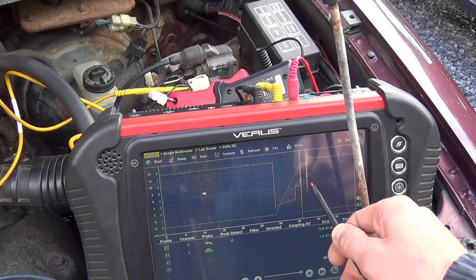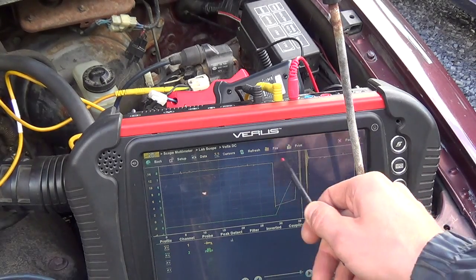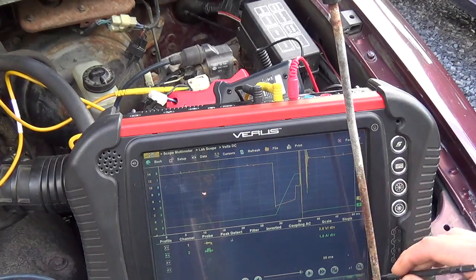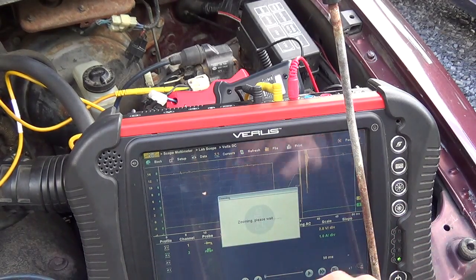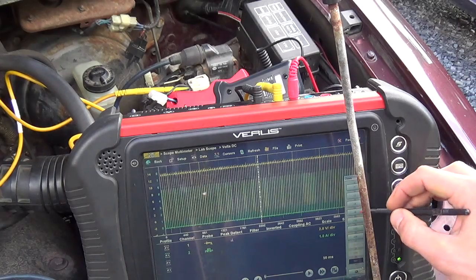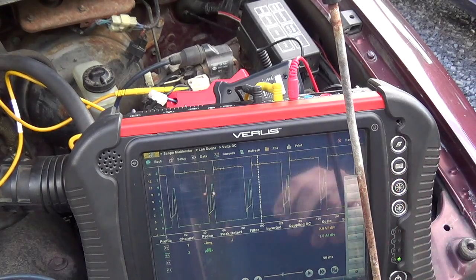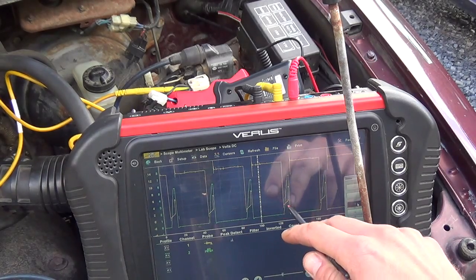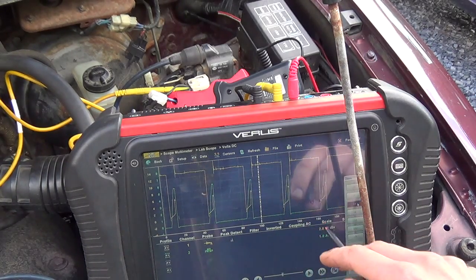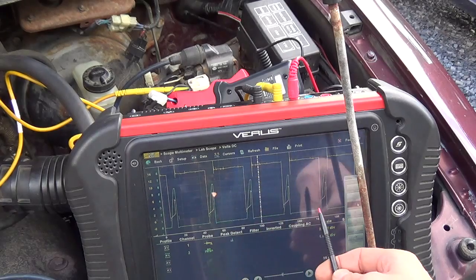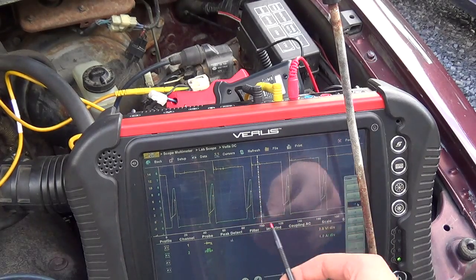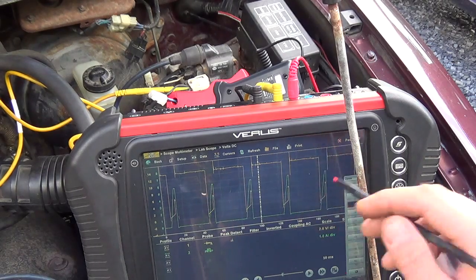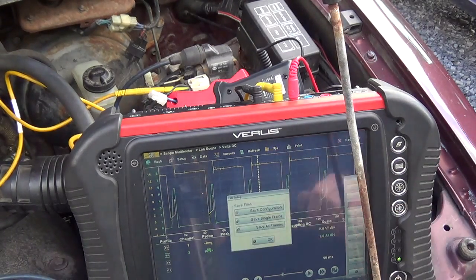So we have to calculate the power consumption for one current ramp. And then we have to see how often the current ramps repeat. You know, because there's this dead time between the firings, and then we have power consumption and then no power consumption again. So we have to see what percentage of the time the transistor is being switched on. So I'm going to save this again and we'll analyze it on the whiteboard.